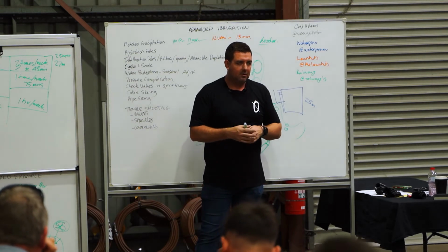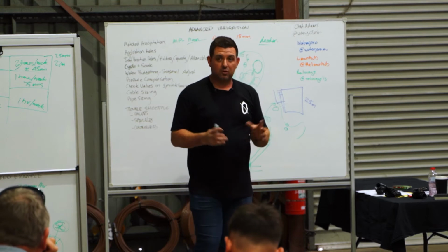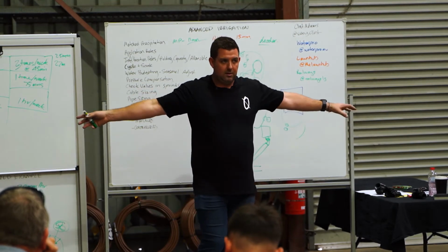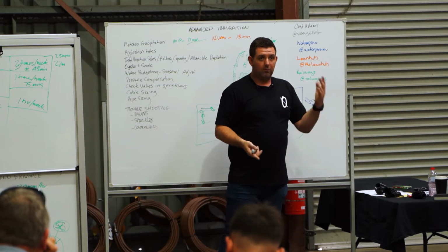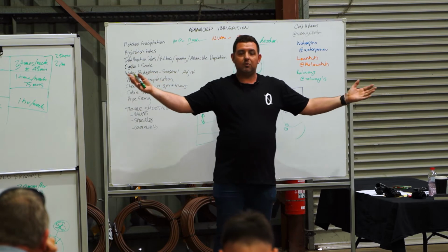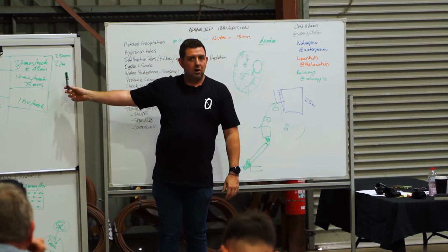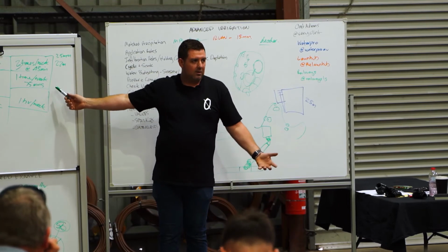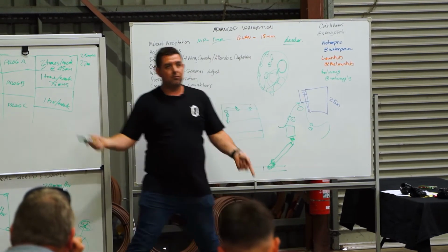So the advantage of that is you only need to run 2 cables. You can run 2 cables to, in most cases, up to 200 decoders around the whole area. It sends the signal out to the decoder to open. You can actually have 4 or 5, I think it's 4 up to 6 with some of them, all open at the same time. With a golf course, you need 25 mil across the whole golf course. You've got 2 different pump systems, so you can actually have 2 valves open at the same time.